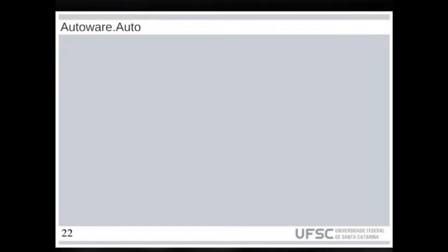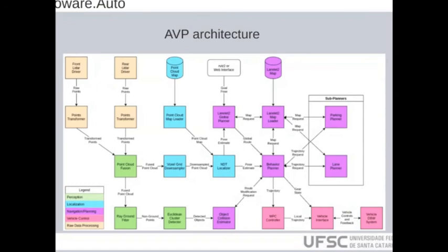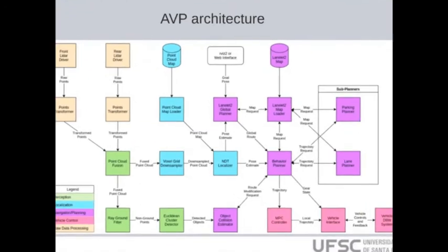Okay, so Autoware Auto was tested after Autoware AI. Autoware Auto is safer and runs faster than Autoware AI because it's based on ROS2. In ROS2 we have a quicker and reliable data distribution service. But Autoware Auto covers specific scenarios, so it was not possible to test in different scenarios. The architecture of the planner is quite similar to Open Planner but different from the other ones.